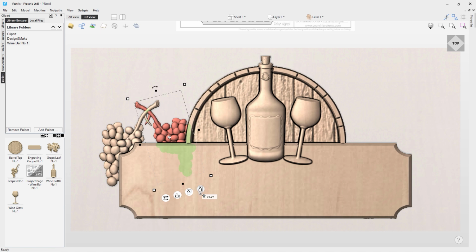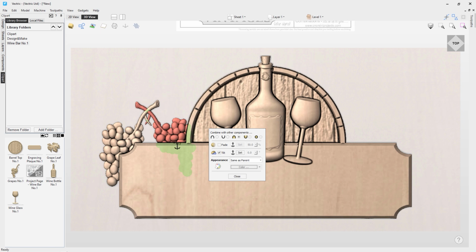So we're going to go for the tilt this time again. So we'll click on the properties here, and we'll go for tilt. Now this time I'm going to set the anchor from down here first to up here for the axis. So let's put in a value. So if I put in 1 degree, for example, hit space. Okay, that did the trick. That looks pretty good. Happy with that.